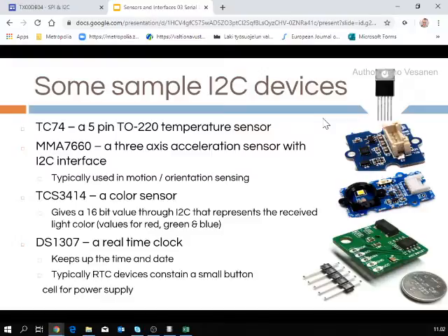Then there are, for example, I think this is originally Motorola, now I think it's Infineon, a 3-axis acceleration sensor that has I2C. It's that small chip here, one of those QFN cans, very tiny, about 3 times 3 millimeters. That's a little bit tricky for soldering, especially with these.